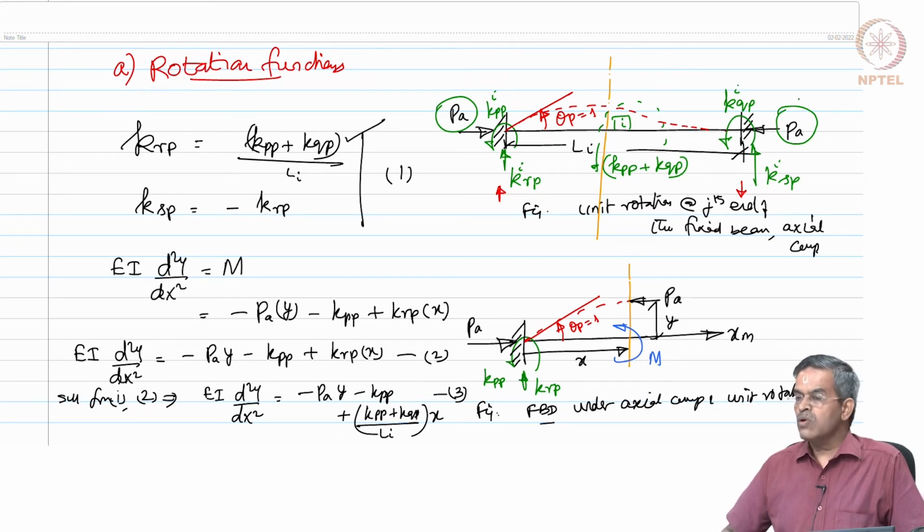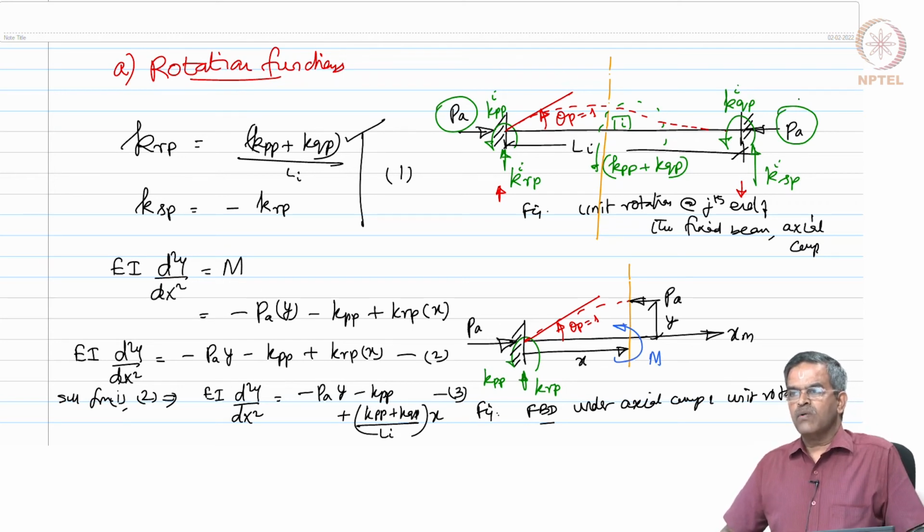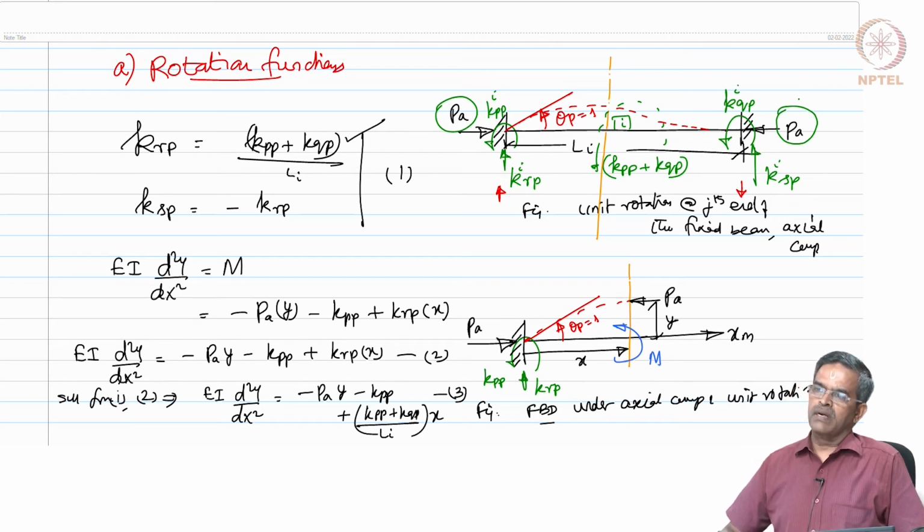So, I will no more call this bending. This is not happening because of any lateral load or gravity load. The profile shown on the screen is happening purely because of buckling, and it is happening on the same plane where unit rotation is given. Is that okay? Then you may ask me a question, sir, why are we estimating buckling when rotation is given?